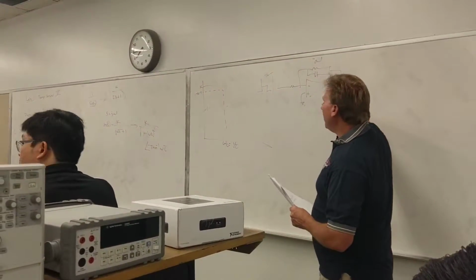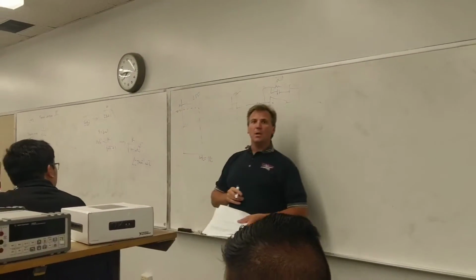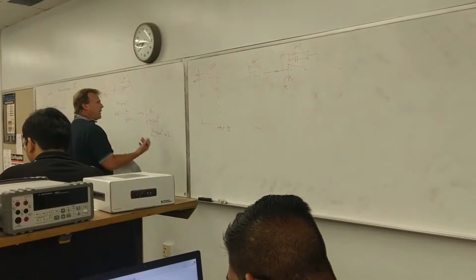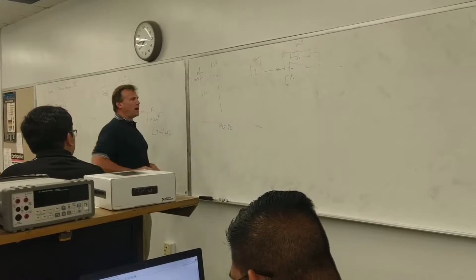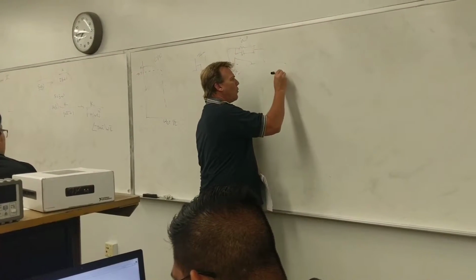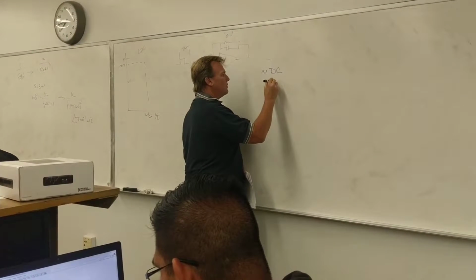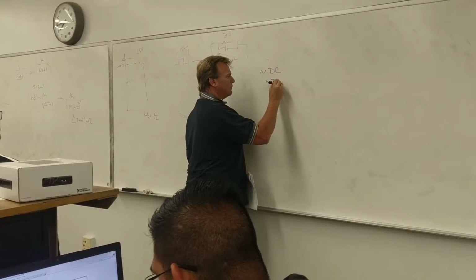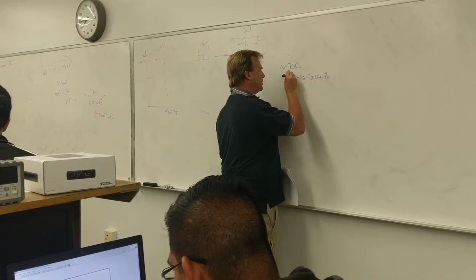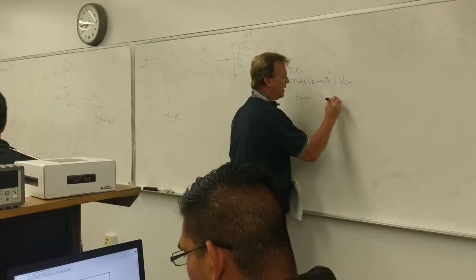Signal to this guy. We know that this is going to have a frequency response of what this is right here, which is a low pass filter. So what we're going to anticipate is, as long as our PWM frequency is higher than that cutoff, what we're going to see on this output voltage is something that's more or less a DC signal, which is essentially the duty cycle percent times the V from the PWM.